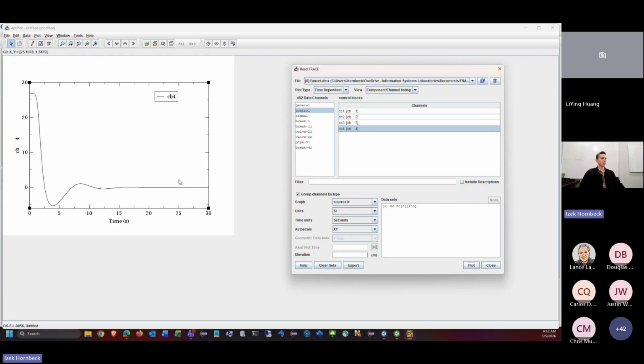So just like that, we can see that that PI controller did indeed bring our error towards 0, towards that target temperature of 310 Kelvin. And you can go in and just adjust your gain values, your tau value a little bit more to kind of fine tune that. You can actually get it to converge towards 0 closer to like 10 to 15 seconds even. And so that kind of concludes this exercise with the faucet model.